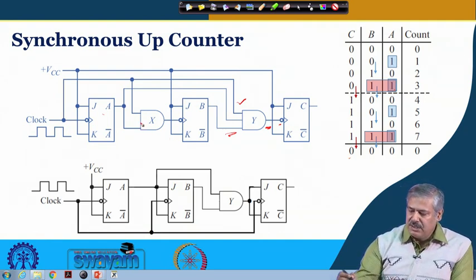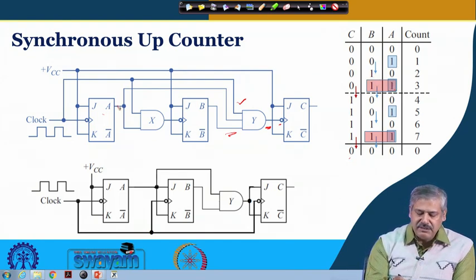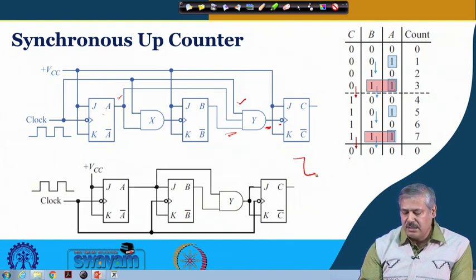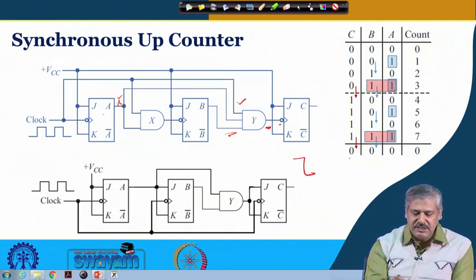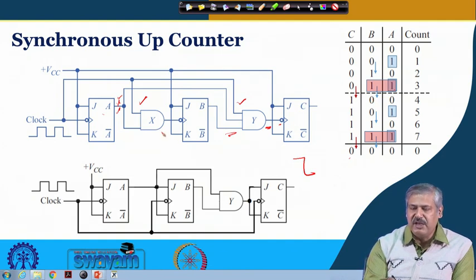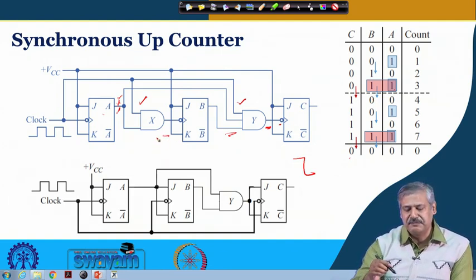So, the value 1, 1 is made available in the previous clock trigger itself. So that way this is not contributing to the delay, in the way that one flip flop's output is not actually triggering the next, it is only the clock that is triggering. A output is just ensuring that the clock is made available. So that way it is behaving like a synchronous counter.